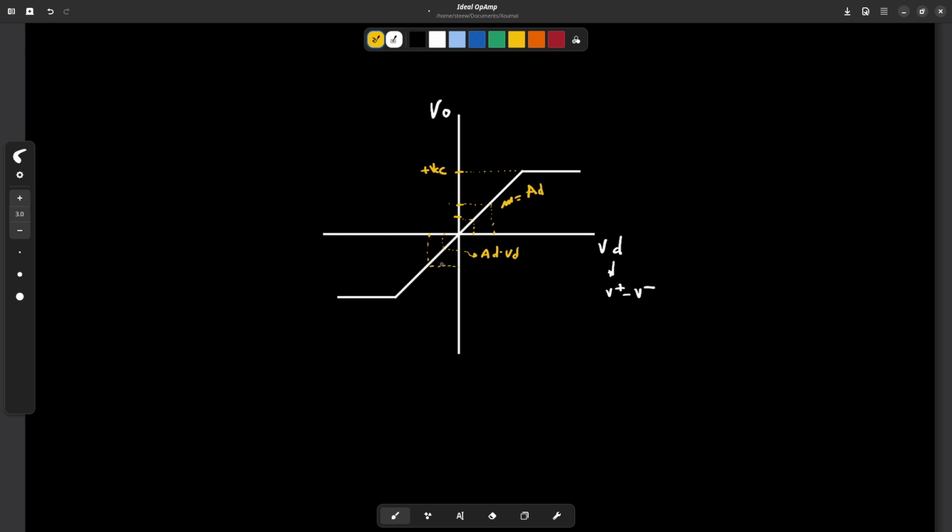So when it becomes lower and lower, more negative I mean, this output is going to be lower and lower, more negative, to the point that the minimum value we can have at the output of the amplifier is the negative voltage supply. In the case of the previous example, which was biased with plus VCC and minus VCC, this minimum value will be minus VCC.